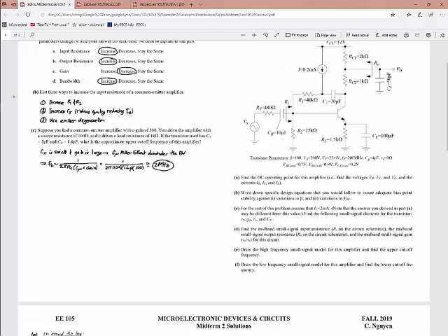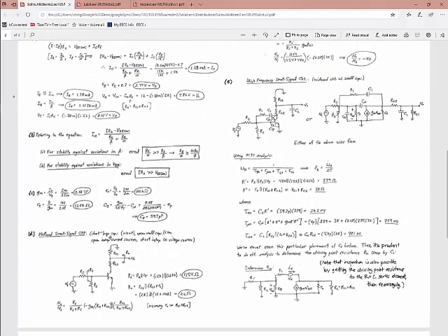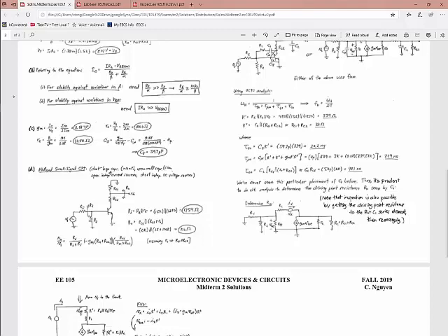Okay, problem number 2, I guess this came down to whether you knew what to do with this current source. You had to open circuit that for the small signal analysis. It also came down to whether you tried to analyze this R1, C1 combination here, which you actually could do by inspection if you knew what you were doing. The solution does it in the brute force method, assuming it's a configuration you hadn't seen before. The best thing to do is just replace the C1 with a voltage source and measure the current across that to get the driving point resistance.